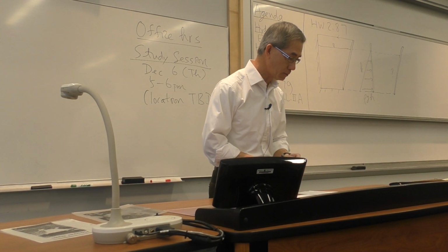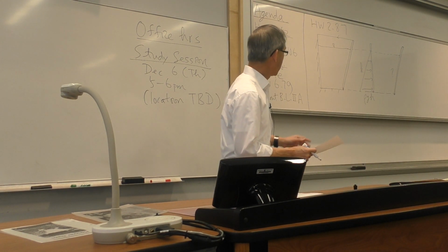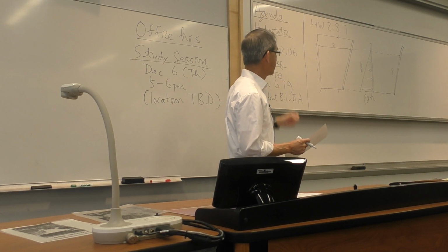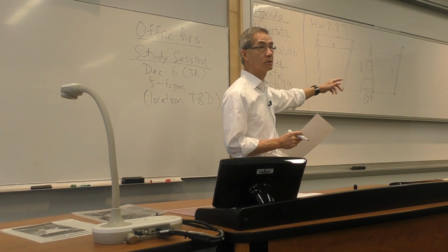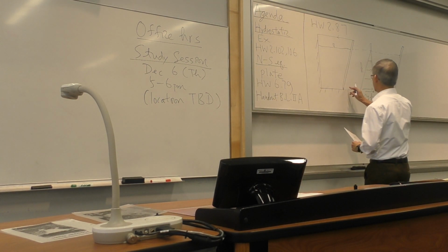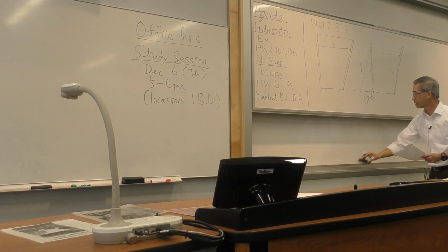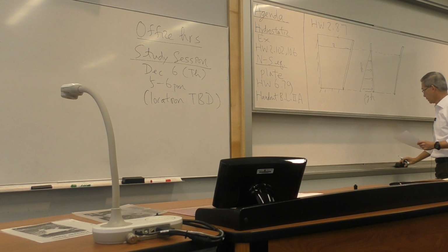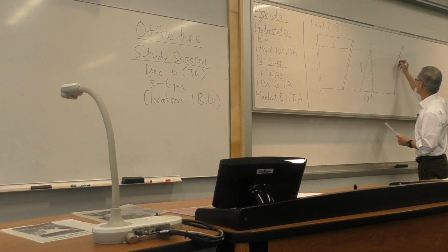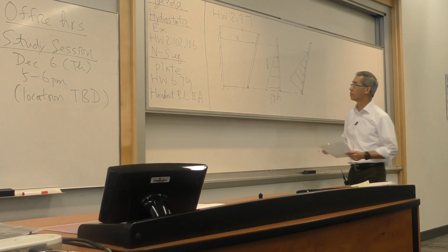So the next problem is a little interesting, but prior to that, I just want to reinforce what we did last time in reference to the homework due today. An inclined plate is different from a vertical upright plate in that the pressure prism is simply rotated, and all the forces you still have to add, normal and perpendicular.